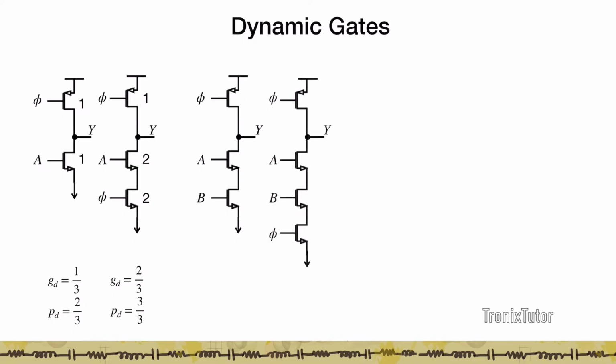If you look at a NAND2 gate, a NAND2 gate can be implemented in an unfooted way by 2 NMOS transistors in series, and in a footed way with 3 NMOS transistors in series. Again, here the sizing would go 1 2 2 as opposed to 1 3 3 in the footed case, with the pull down logical efforts being 2/3 and 1 for the two cases.